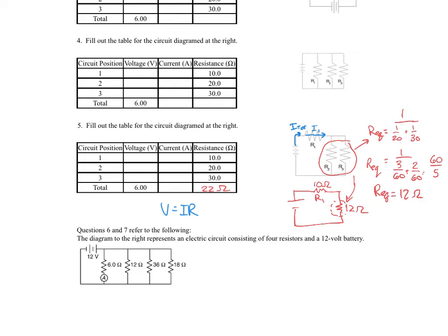So once we get this I total, these two boxes are going to be identical because the amount coming out of the battery has to go across that R1. And it's also going to come back to the battery as I total over here. But that's just keeping track of that so far. We'll go back and solve for I2 and I3 later, but let's get this done first.